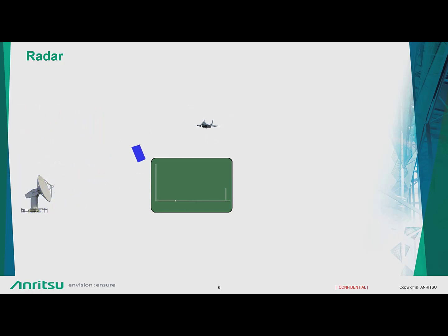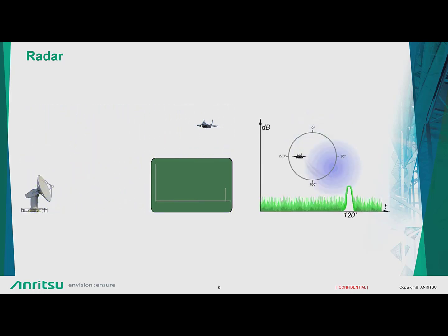So the range and the distance is what radar determines. But apart from that, this piece of information is not sufficient. You need to know in which direction this particular object is flying, approaching or exiting. For that, in the previous world, these antennas which were kept on top of, say, a military truck or somewhere else, kept on rotating.